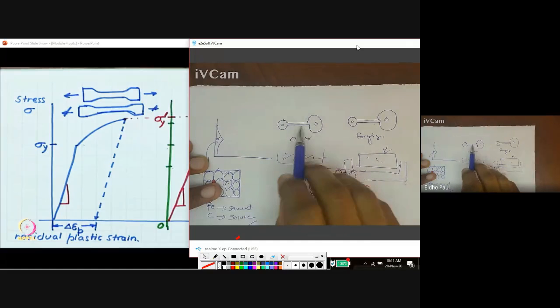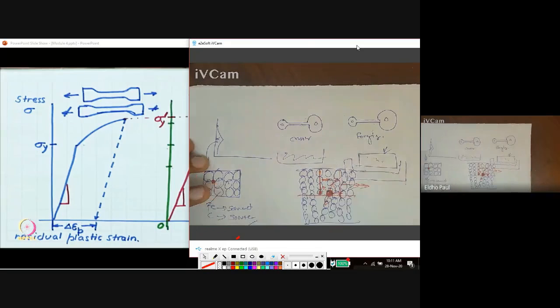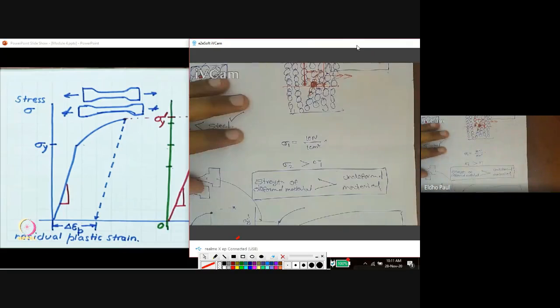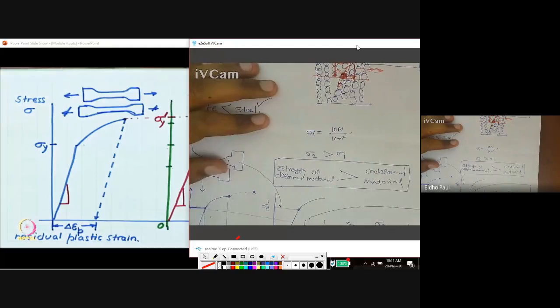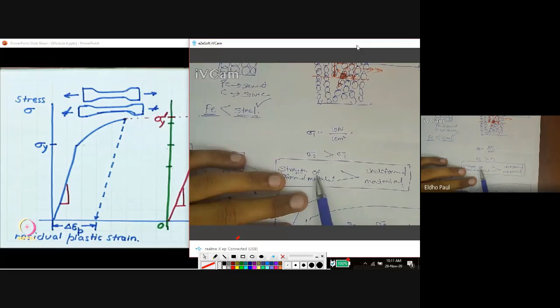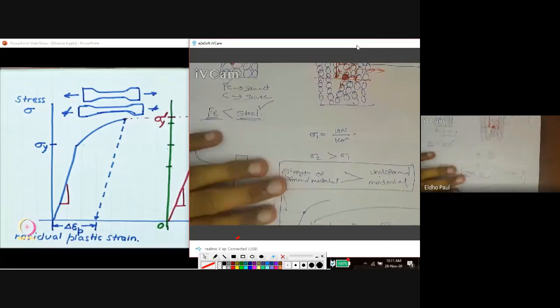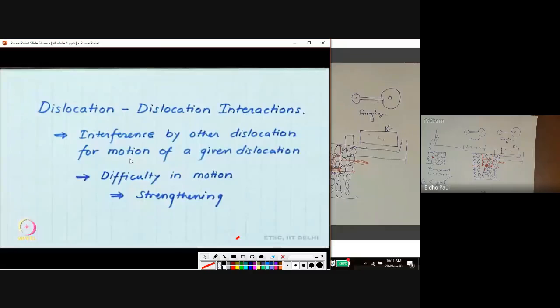So there is no plastic deformation for casting, but here we have a huge amount of plastic deformation. By this plastic deformation, the strength of the deformed material is increased over the undeformed material. So the forged component has higher strength. That is called strain hardening.